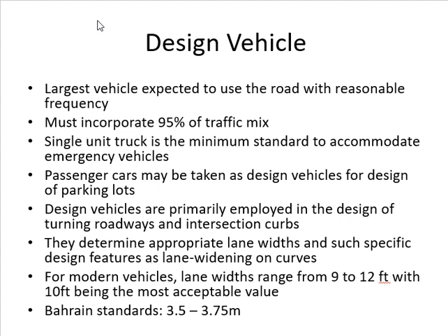What else? The normal width of the road is something else, and the width of the road on a curve is usually larger. Again, because of the design vehicle. A truck which may need, let's say, 10 feet on a straight road, when it comes to turning, it cannot make the turn within 10 feet. It's too small, so it needs more space. We call it lane widening.